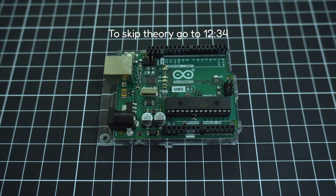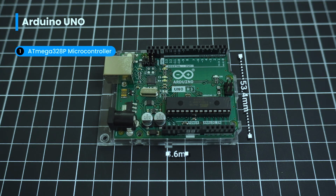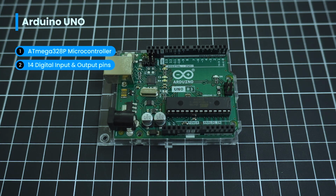The Arduino UNO is a widely used open-source microcontroller board based on the Atmega 328P microcontroller, with a dimension of approximately 53.4 mm by 68.6 mm, making it compact and suitable for a wide range of projects. The board features 14 digital input and output pins, which can be used to read digital signals or control devices such as LEDs, relays, and motors.